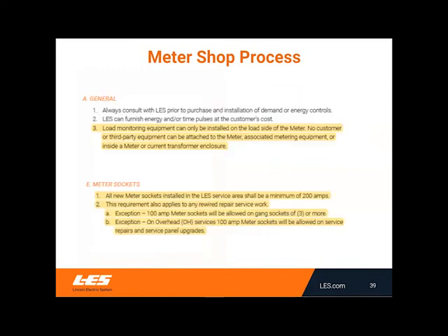All right. And so a couple things to highlight in the meter services spec guide. Ray just mentioned this regarding load monitoring equipment. Again, I'll reiterate, just stay out of the meter socket or any sort of meter enclosure, CT cabinet. We want to keep that free of those sorts of things. And then again, we want to remind everyone about the meter sockets. On new services and rewires, we do require that 200 amp rating on the meter socket for single phase residential services. And there are a couple exceptions, but those are noted in the meter services specification guide.